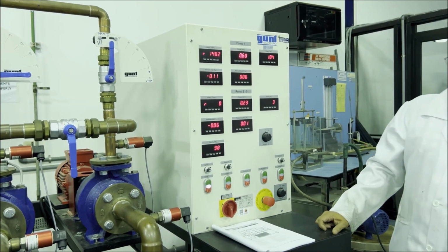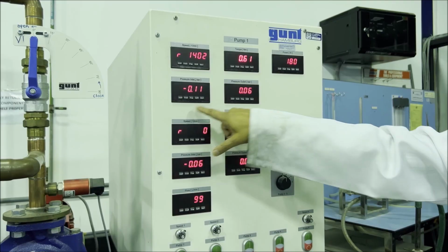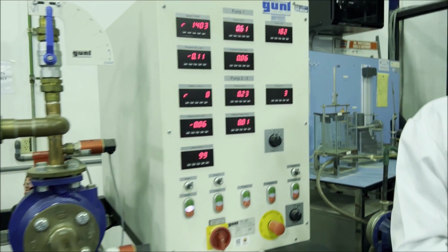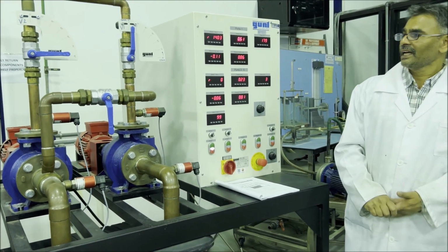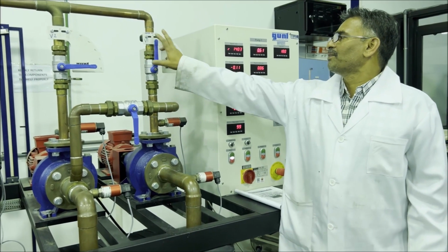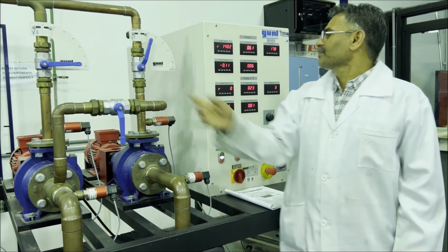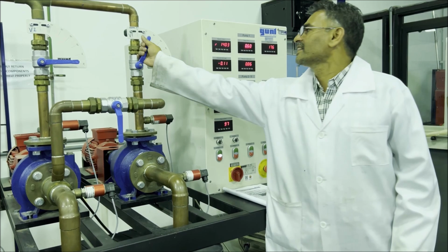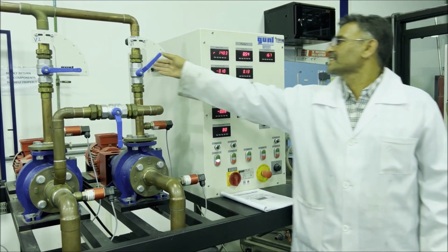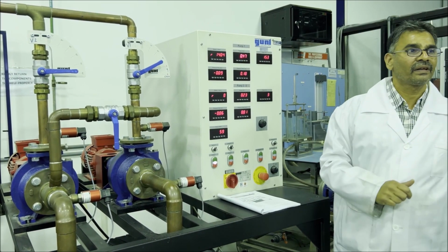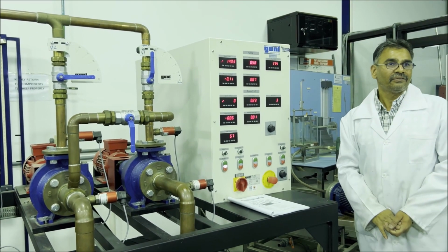Yes, 1400. So here we will get discharge, here we will get torque, here pressure at the inlet, pressure at the outlet. So open your observation table and record these readings. Then I can open this. The first reading, 0, means fully open. Then I will decrease this slowly, 15, then measure all the readings, then 30, measure all the readings, then 40, measure all the readings, 60, measure all the readings. Understand? Very simple. Now I will make it again fully open and take the readings.